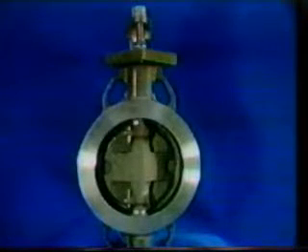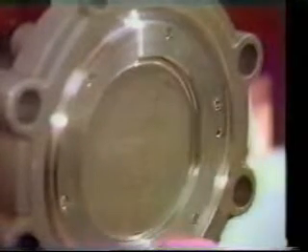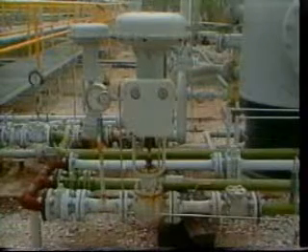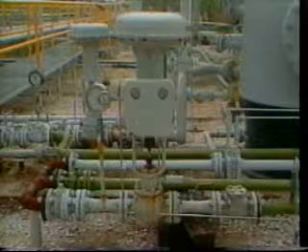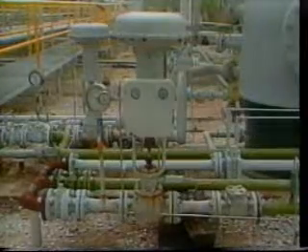There are numerous miscellaneous valves that have application in flow lines. The butterfly-type valve is a shutter-like control device that is suited for low-pressure liquid applications. This valve is opened or closed with a quarter turn. The use of a butterfly valve is limited but is excellent for tank inlet and outlet valves. The diaphragm valve is designed so that the flow of fluid is directed over an indented weir that closes the flow when the diaphragm is brought down and compressed against it by the operating mechanism.